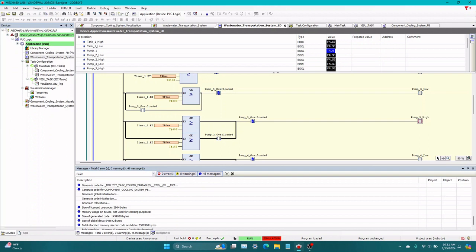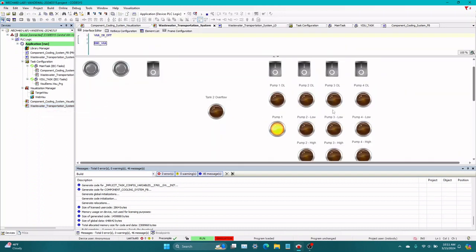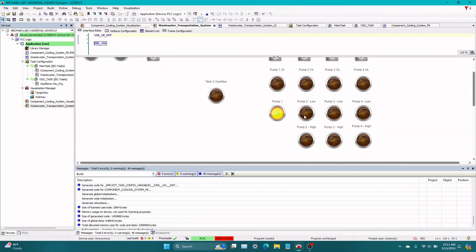That's because if we go back here, the high speed for pump 3 normally would be after 15, 30, 45 seconds. Or if it goes right to pump 2 after 15 seconds, but pump 2 is overloaded, it will switch over to pump 3. So that is the thought process there.